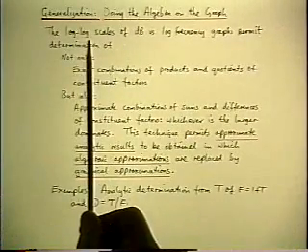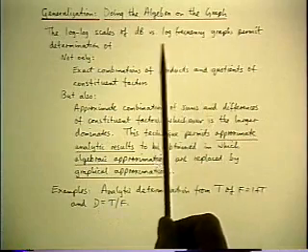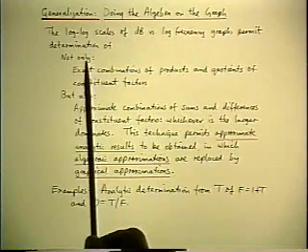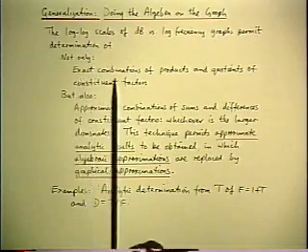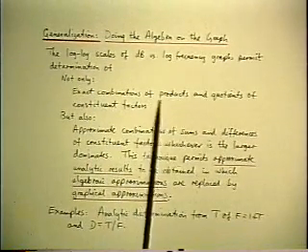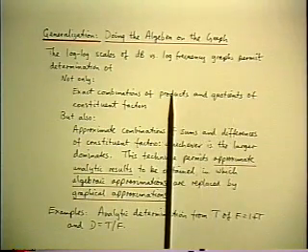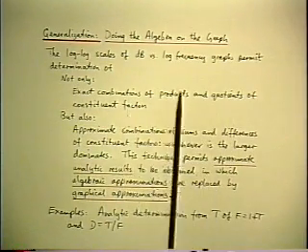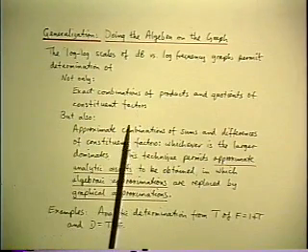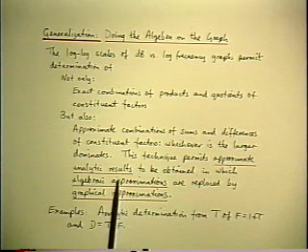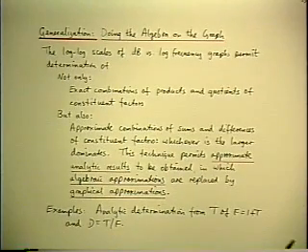So notice that using log-log scales for dB versus frequency permits the determination not only of exact products and quotients, because products and quotients convert directly into sums and differences of dB, but now you see how you can also do it to compute sums and differences. A technique that no one emphasizes in the textbooks.